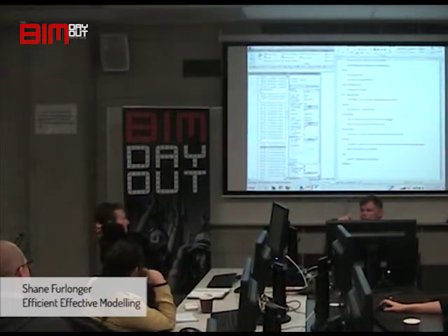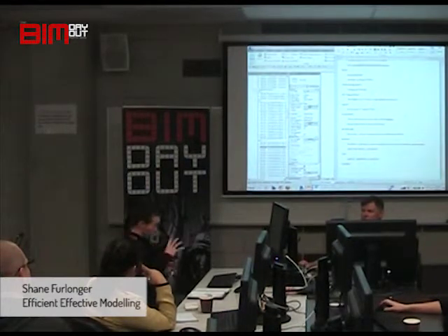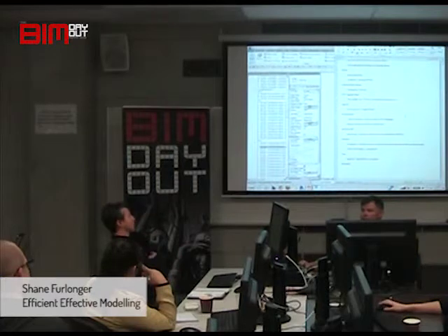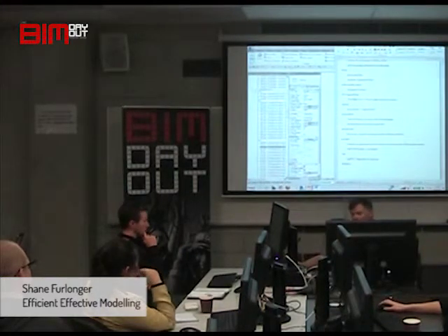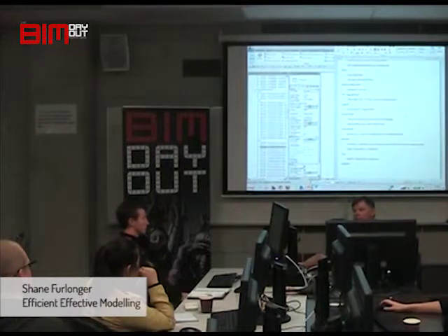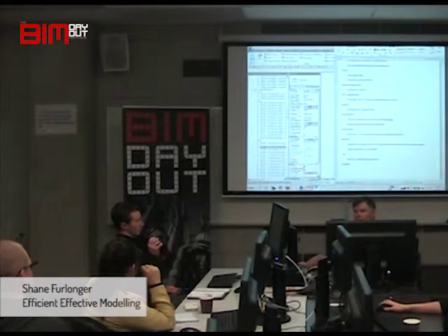Can I ask though, if say for example you're putting keynotes on elevations, do you keep it very generic and then let your detail go into more depth for it, or is it all refer back to specs? Yes. You can link your keynotes to your specs. So in the large format scale you keep it generic and then your details are much more specific, yeah.